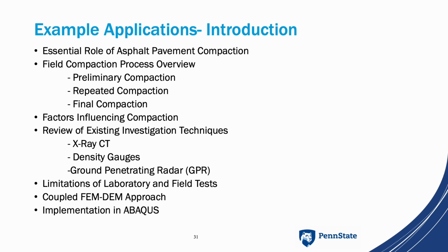Factors that could influence the compaction process are, one, properties of the mixture composition that I said, like AC11 and PA11, two, environmental conditions, and third, compaction methods. If the angularity, size and hardness increase, then the compactive effort also increases. Compaction is defined as the gaps between the particles shrinking. The air between the asphalt particles is continually removed.